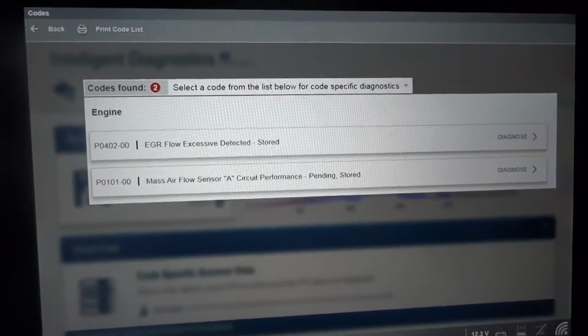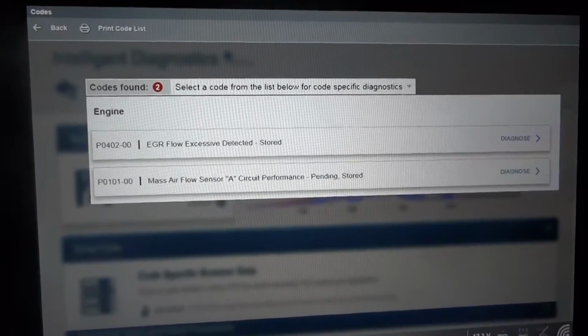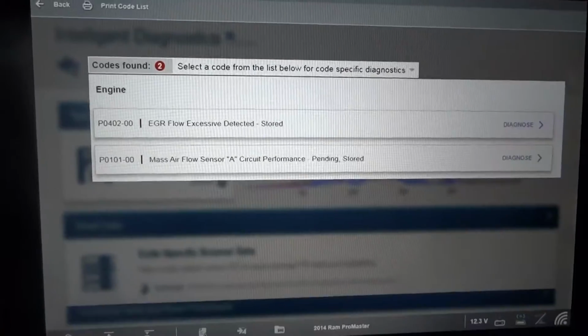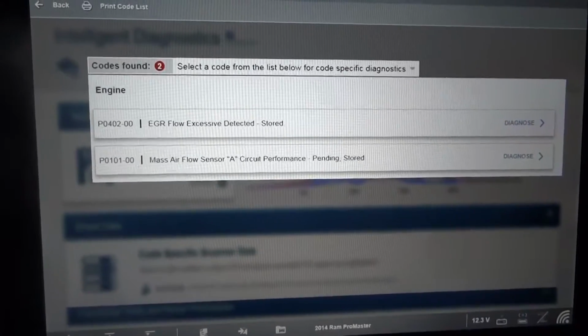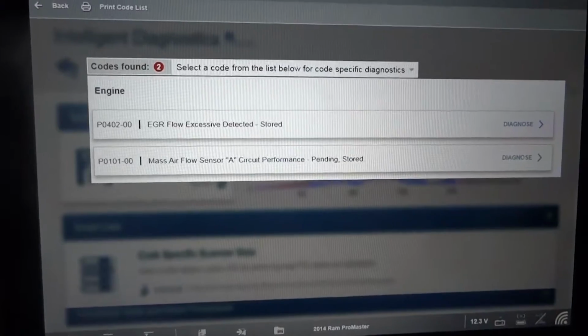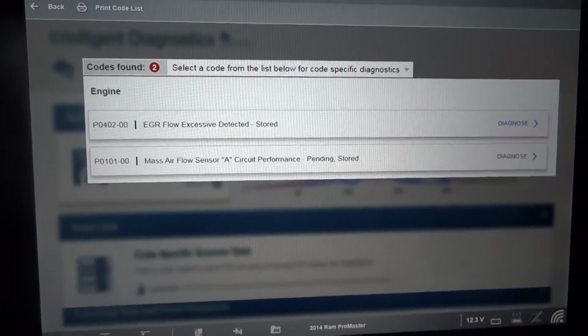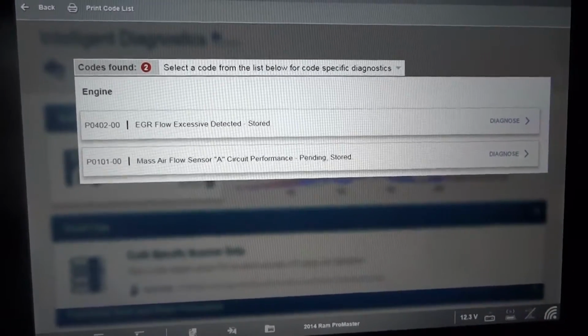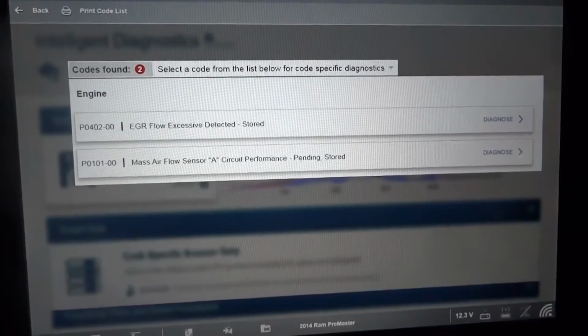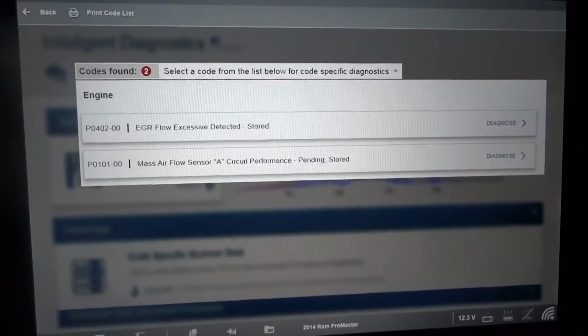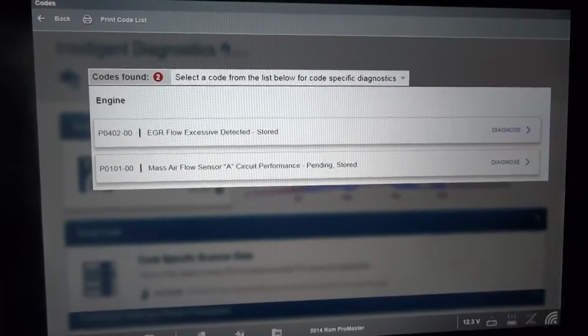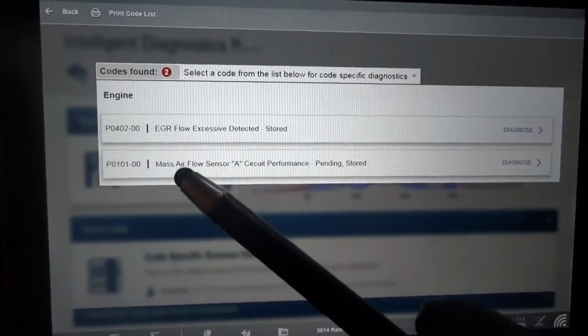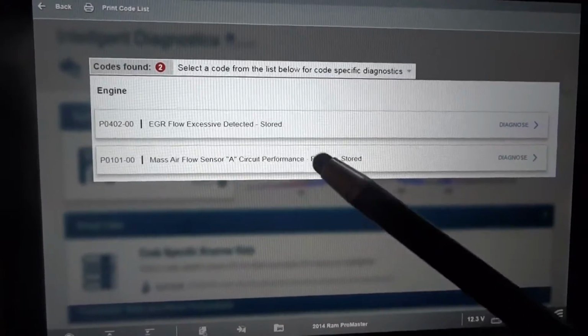Some of them have a temperature sensor after the EGR valve. The computer also looks at the mass airflow sensor input when the EGR valve opens. And on the EGR valve assembly, there is a position sensor that tells the computer the position of the valve when the valve opens. Okay, now I believe on this model, the computer looks at the input coming from the mass airflow sensor.